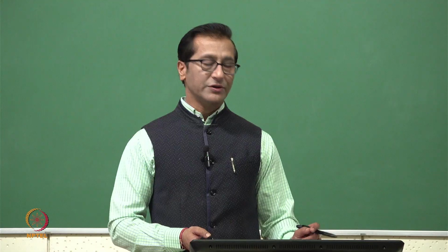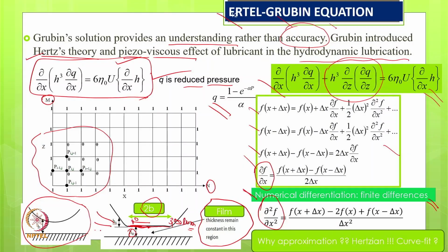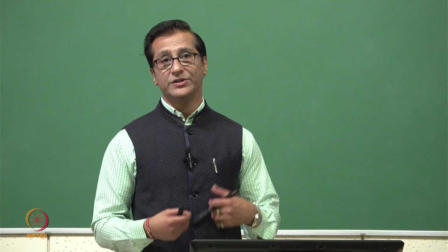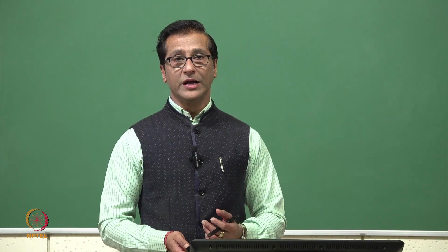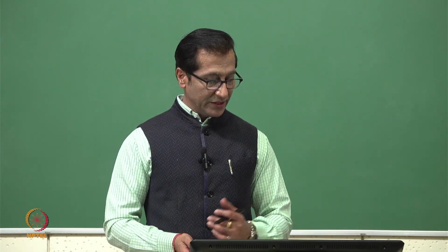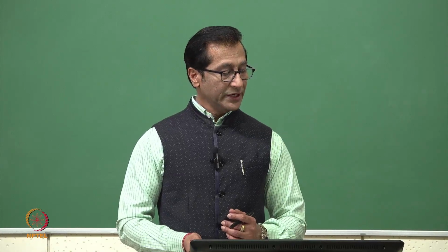So it is not only the conversion. We are assuming there is a conversion zone, but after that there is a stationary kind of zone, where the pressure only gets developed and becomes significantly high, where the piezoviscous effect also happens. So that's his assumption, and he tried to give a solution based on that.